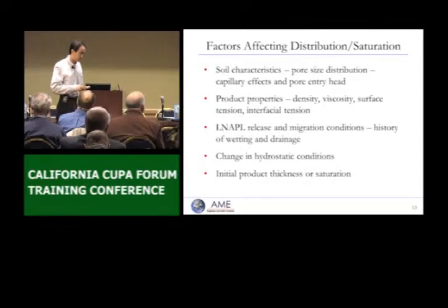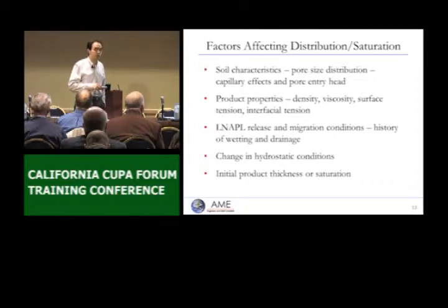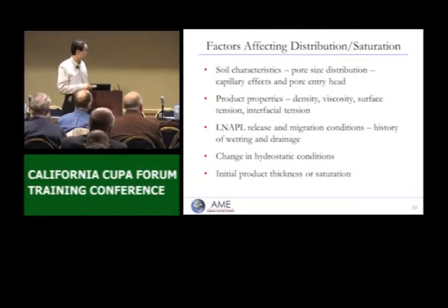Another thing is LNAPL release history and migration conditions, which says the history of wetting and drainage has an influence on the saturation and distribution of the oil in the subsurface. They have studied something called hysteresis, quite complicated. Also, changing hydrostatic conditions play an important role in the saturation.